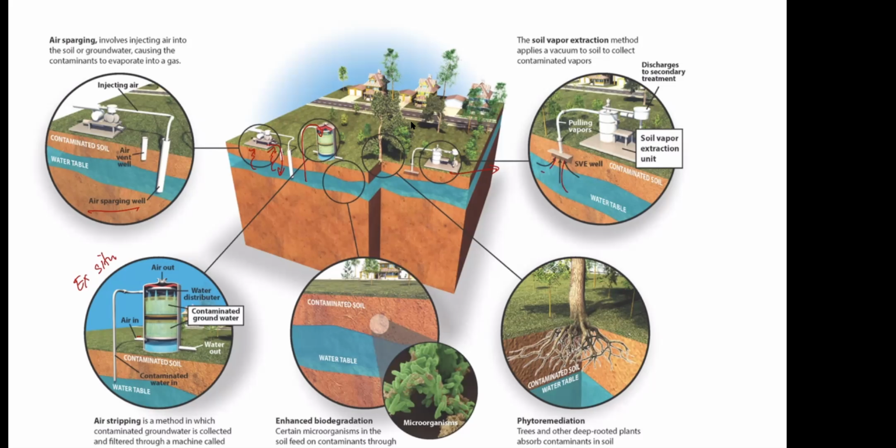In situ techniques, instead of taking all the polluted water, and pumping is expensive. Pumping is not just expensive because you have to spend a lot of energy, it is also inefficient, because when you pump the groundwater, no matter how efficient your pumps are, it may not draw all the contaminated water, because there are pores that will hold on to that water for a long time.